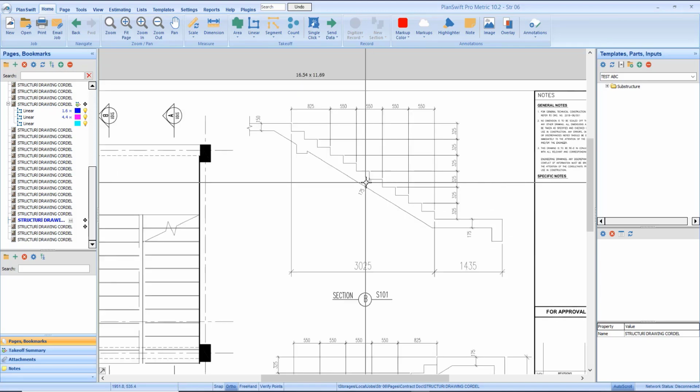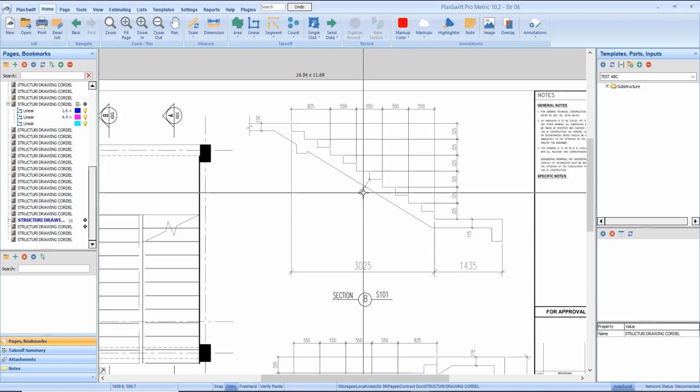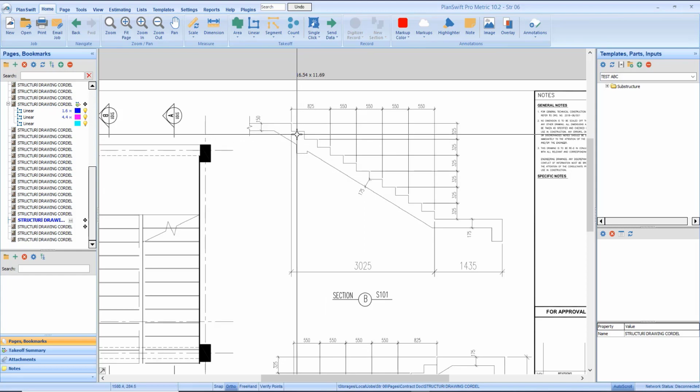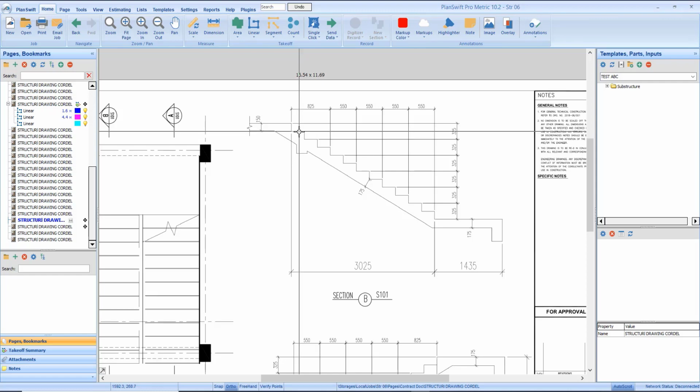The concrete work for your staircase, you take it off as a composite item. And what do I mean by that? You don't take off each of the risers and you don't take off each of the treads, except if you are measuring for your treads and risers in terms of your finishings. So for you to take care of your concrete work, you will have to take care of it as a composite item of work. Let me go ahead and show us what I mean by that.